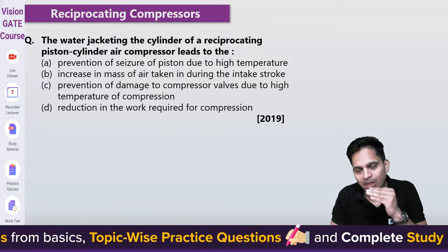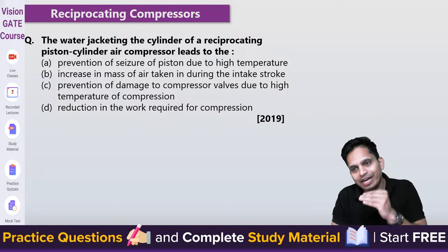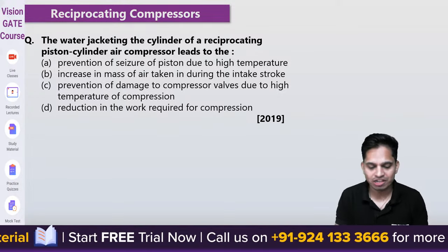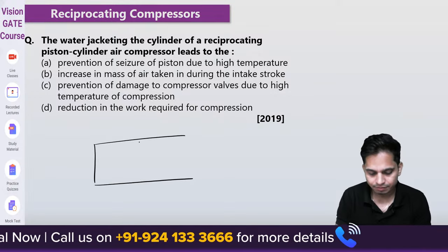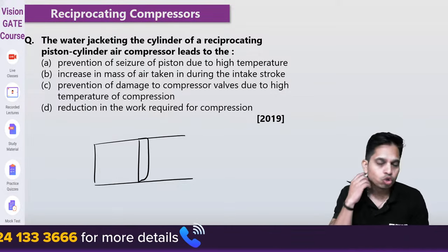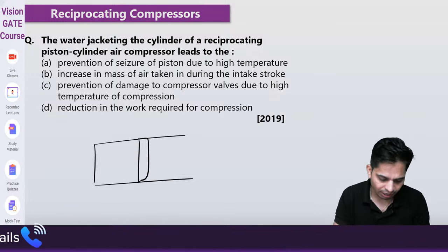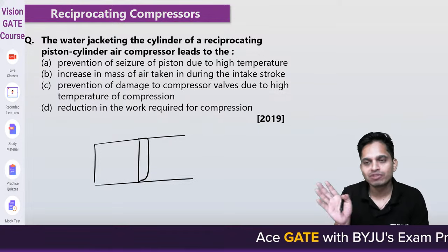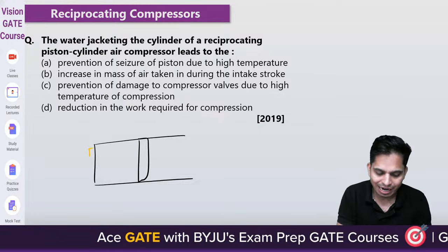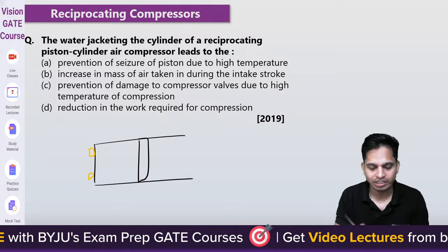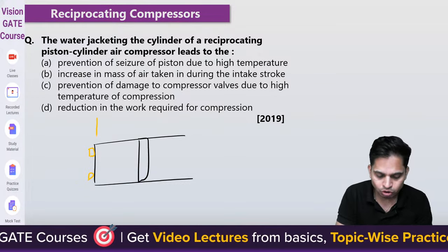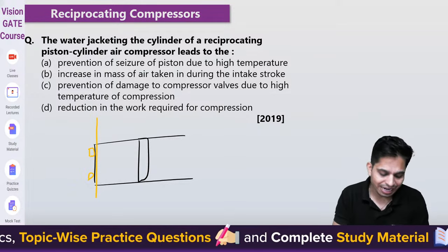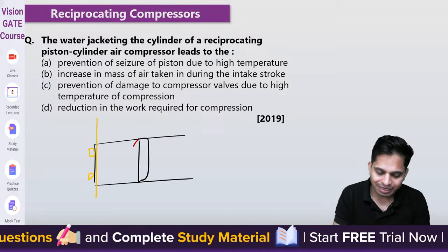So if it expands because of thermal expansion, it can go and hit the cylinder wall. For example, if this is your piston, so you design your piston maybe something like this, that okay, I am giving no clearance, because usually your valves do not need clearance. Your valves are here outside, they can operate outside easily. You can plan that your piston should stop exactly here, good, no problem. But if temperature is really high, then it can expand.